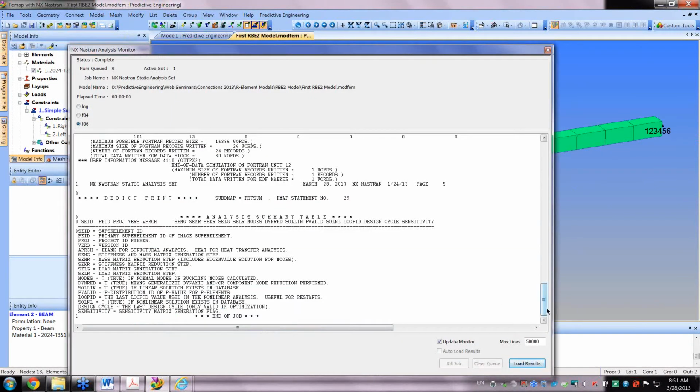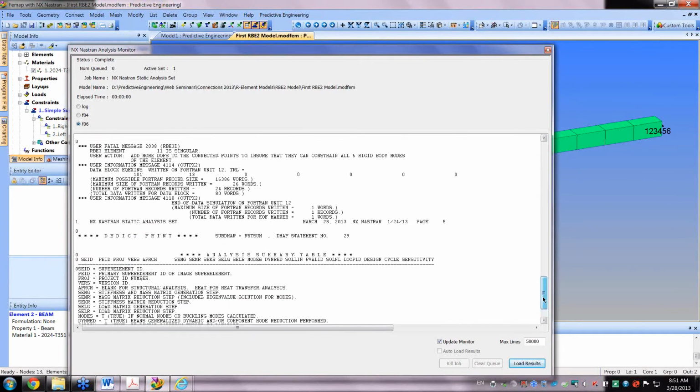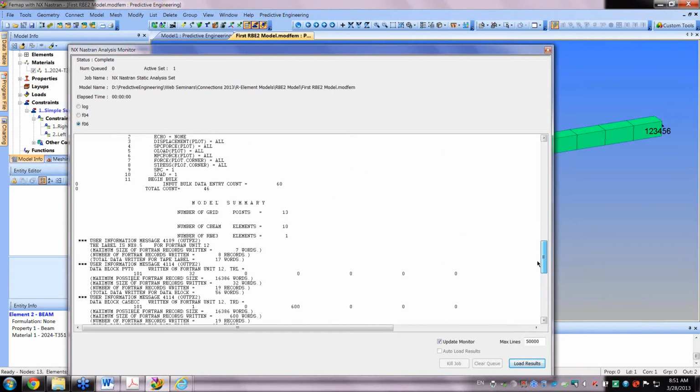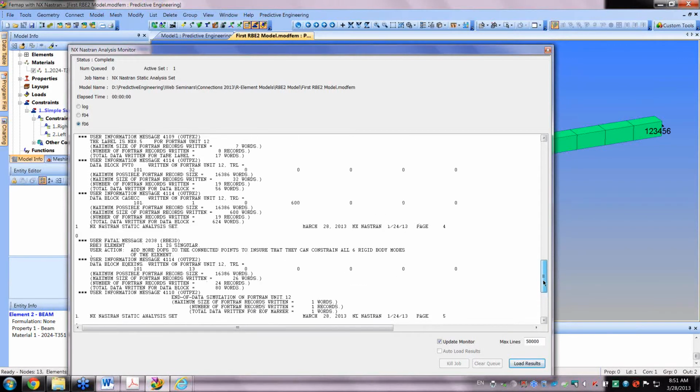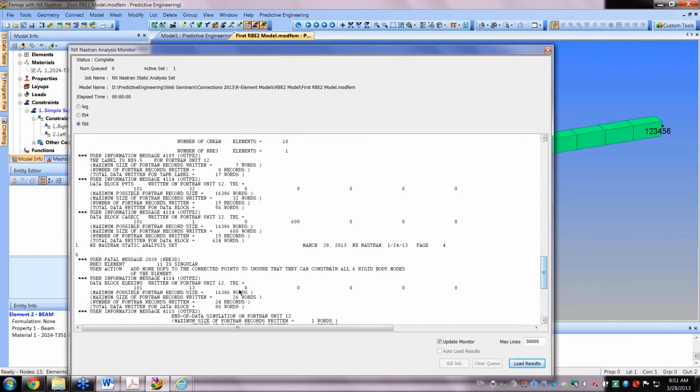You're making a stiffness, a relationship among the dependent and independent nodes, that has to be stable. In an RBE2, you come out of the gate with the independent nodes having 6 degrees of freedom and completely stable matrix-wise. It always comes out of the gate stable in the matrix. In an RBE3, since you're defining degrees of freedom on the independent nodes, it doesn't come out stable. And that screws people up all the time. It's one of the big dangerous parts.